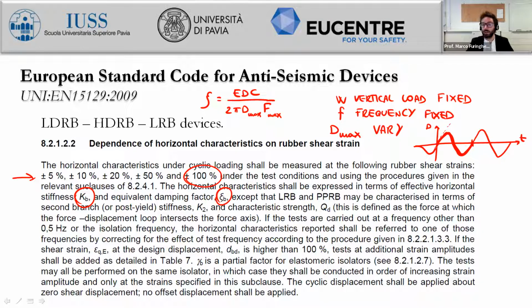which is not accounted as a fully fledged cycle, but it allows the testing equipment to have exactly that value of velocity and 0 displacement at the starting point of the input signal, and at the same time we have an ending loop.